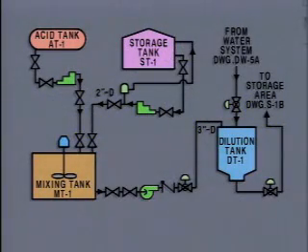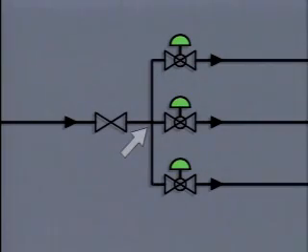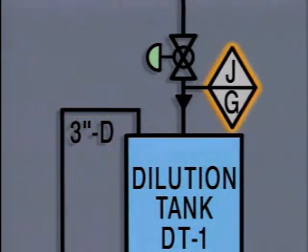The symbols for the valves and other equipment on a process flow diagram are connected by lines that represent the flows of materials in the system. Lines that cross with a hump or a break in one line represent material flows that are not connected. Lines that cross like this, without a hump or a break in one of the lines, represent flows that are connected. The same material flows in all 4 legs of the piping. Some diagrams include codes which indicate piping diameter, or the piping material specifications. The codes are helpful in locating and identifying specific pipes in a system.